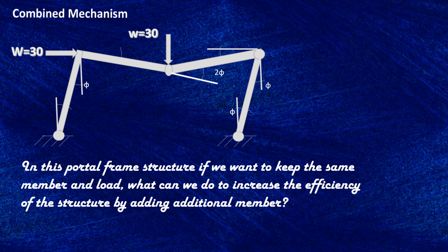We provide bracing. The way we provide bracing is from this joint to this joint, then we can keep the member safe. We can provide a different bracing system, or we have to increase the size of the members to withstand this load.